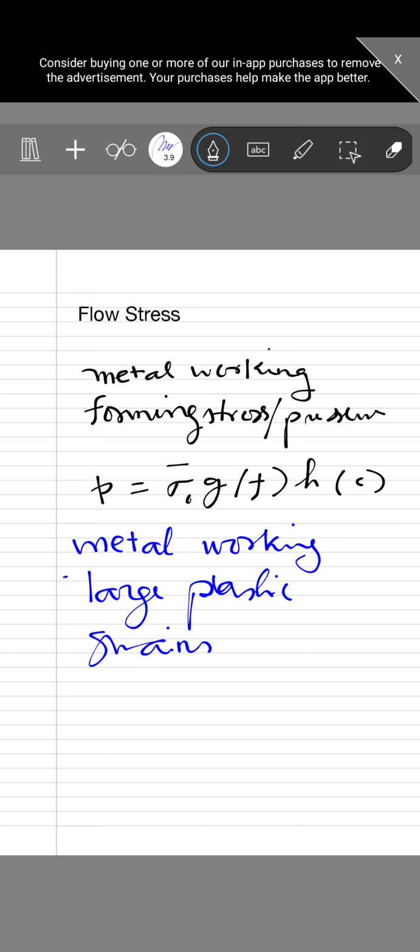And so the flow curve or the flow resistance is the main objective of this lecture. The flow resistance has to be measured when the true strain has gone to a value of 2 to 4. That means the elongation or deformation has taken place to about 2 times the original length.